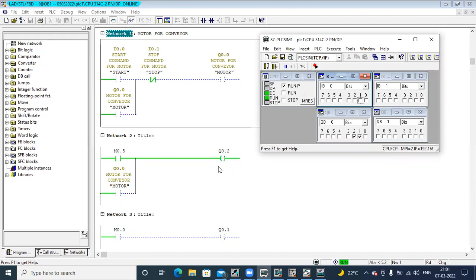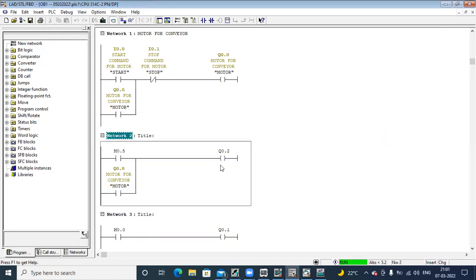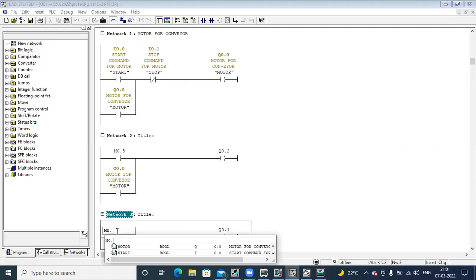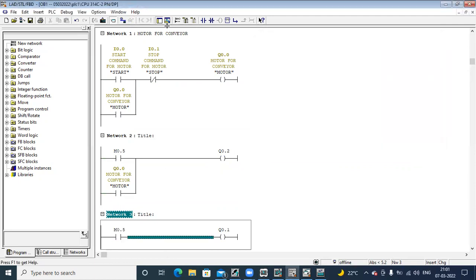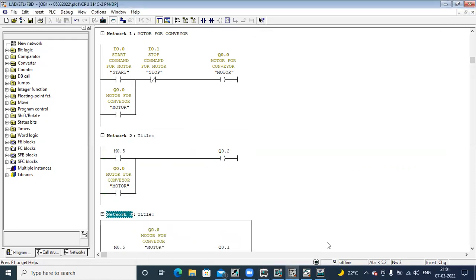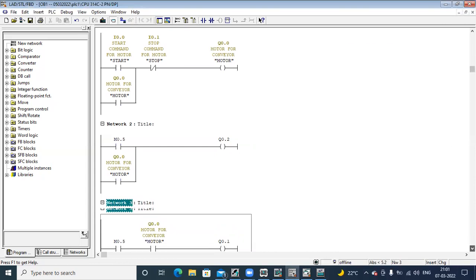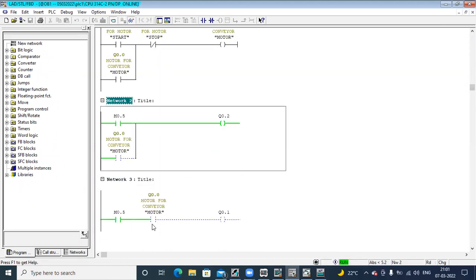So we are having one lamp indicator for motor status. When motor is off, it should be flashing. In other case, I don't want to show flashing if the motor is off. I want to show the lamp is off state even if the motor is off. So here I take the output in series with the flasher. Another example.